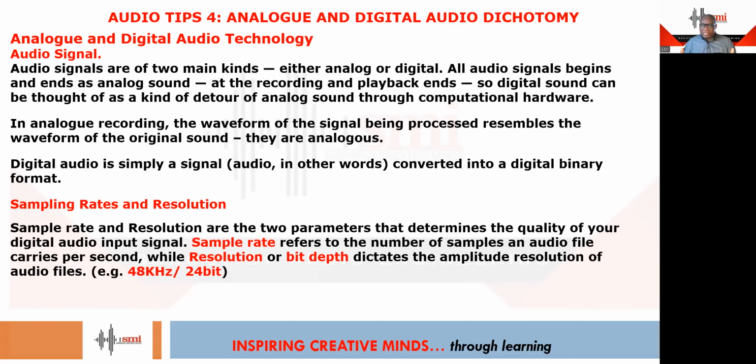So there are two things that your digital device is actually capturing. One, the amount of quality that you want to capture within a second from that signal. Then in that signal, how qualitative the resolution of the amplitude is. It's what we call the bit depth or the resolution.